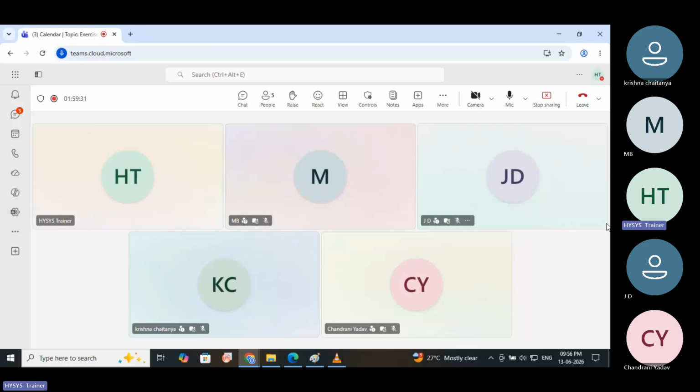The second part is solvent regeneration. The solvent, which is rich in acid gases, is passed through a distillation column, from where the acid gases are removed from the top, and the amine solution, which we call the lean amine solution and which does not contain any acid gases, is removed from the bottom. That solution can be mixed with water as well as amine, and it can be recycled back into the system.